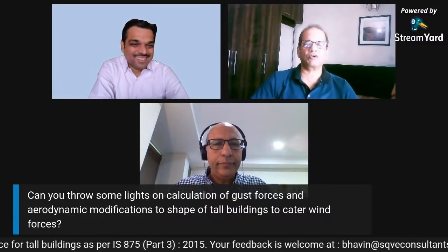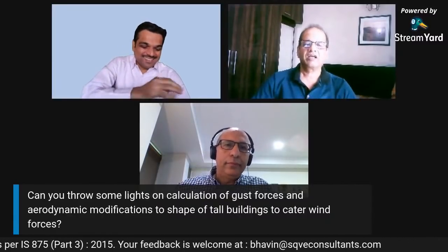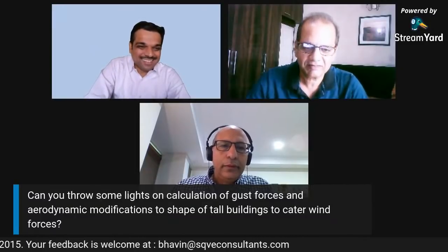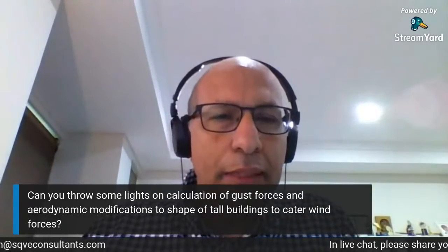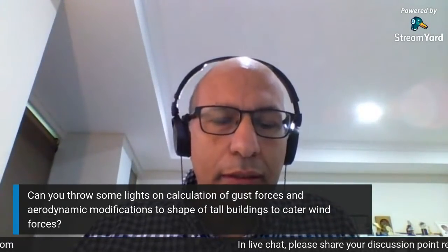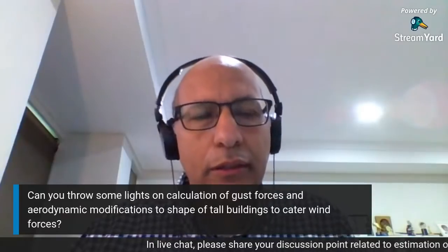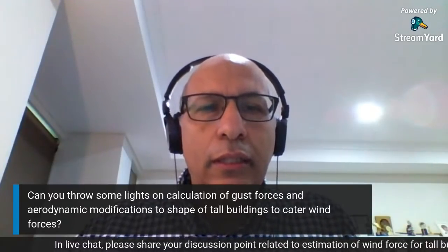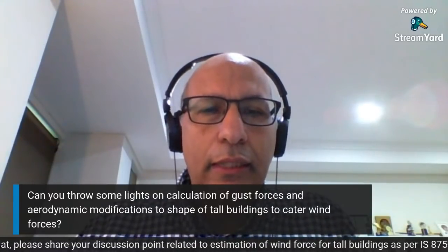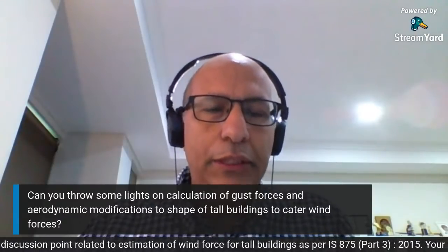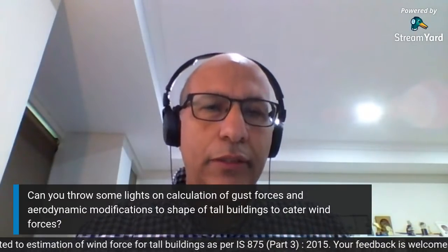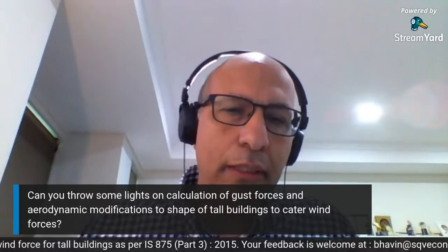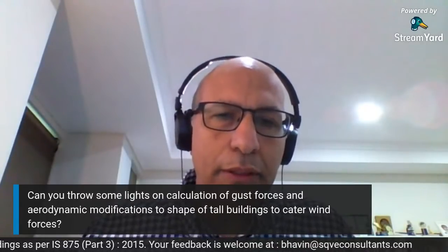Correct. Right. This next question is very interesting, and I'm sure Dr. Tony Rockwell has a lot of information on this. Aerodynamic modifications. Yes, there are very good tricks that could be implemented and have been in the past on some of the very tallest buildings in the world. And a lot of it obviously has to do with the shaping. So the shaping of the tower has a very big impact, more than the structural system.